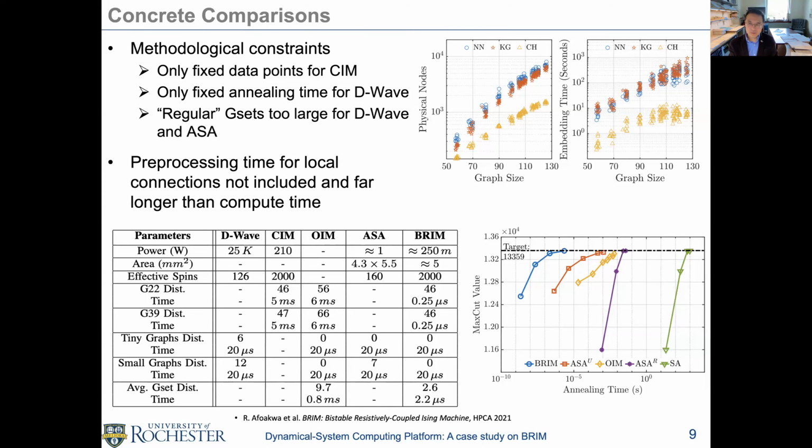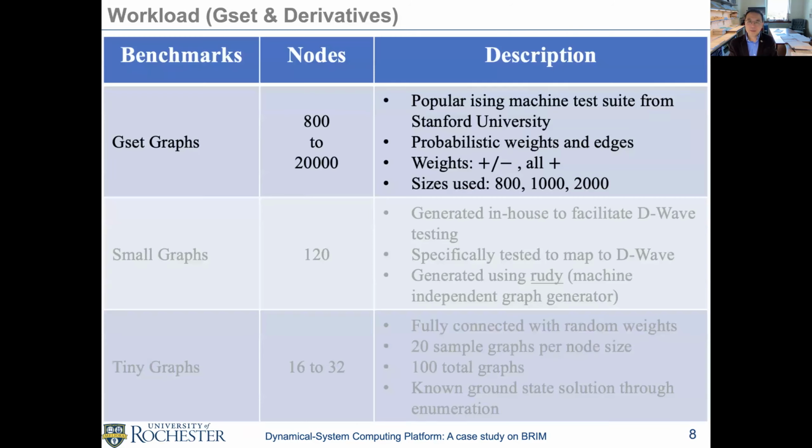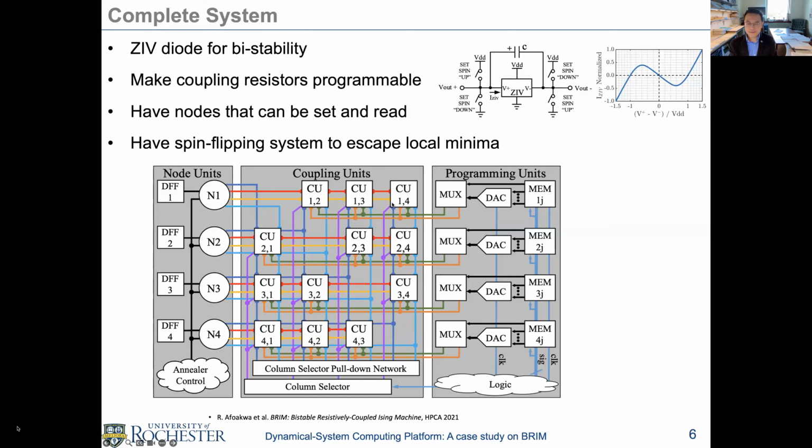My worry is about coupling. The capacitors, I'm not too worried about. You can give me other capacitors, great, we'll play with them. But how do I achieve the coupling, which, first of all, is O(N), so I need a lot of them. Second of all, I need them to be reasonably accurate in coupling. And I think that may be the challenge in the quantum regime. I think that's partly why D-Wave has very few couplers per node, and that's not really solving the problem, it's avoiding the problem. So for an N-node system, you really need N squared couplers, and they have to be reasonably high performance, meaning very easy to control, very stable, and all that. That would be the difficult challenge if I want to go to quantum regime.